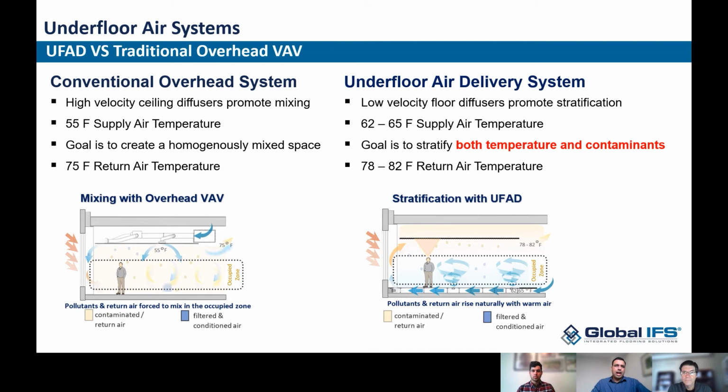So again, these are very contrasting systems. With one system, you're trying to create a homogeneous mixed environment. With the other, you're relying on the natural phenomenon of heat plumes rising over a surface and using that to condition the occupants. And you're stratifying not just the temperature within the space, with the coldest air at the floor level and the warmest air up at the ceiling level.